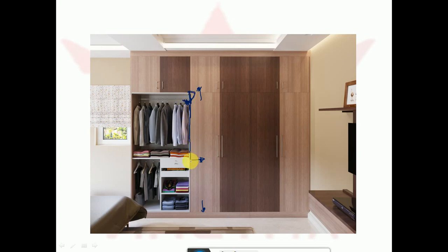This is the support, the vertical support. Here hinges are provided. This is the day-to-day use of a hinge support. A hinge support is the support where vertical motion and horizontal motion are restricted, but rotational motion is allowed. Here your door will rotate about this support, but it will not move upward or downward, nor horizontally. Vertical and horizontal movements are restrained, and the door is only allowed to rotate here. So this is the day-to-day example of a hinged support.